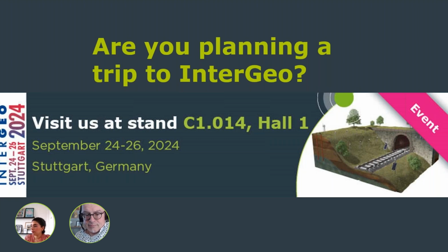Okay. Another one is, can these sensors measure absolute displacements, or can they only detect relative displacements? I would be interested in what's an absolute displacement. So basically, of course, monitoring is always relative, meaning you have a reference measurement, that can be a certain value, 100 meters, and any deviation from 100 meters, but usually you baseline the value, you put it to 0 and see how it changes from that value.